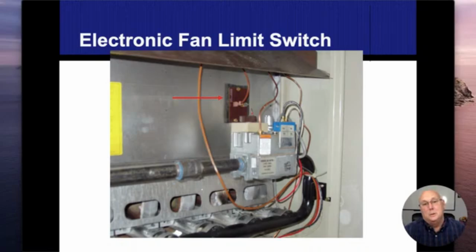The manufacturers of these furnaces and the engineers that put all these things together know how long it takes before the heat exchanger heats up. Whether it's 20 seconds, 10 seconds, or 30 seconds, they let the computer decide. We're going to light the flame, make sure that the flame is lit, and make sure we're getting some heat and the temperature is rising.